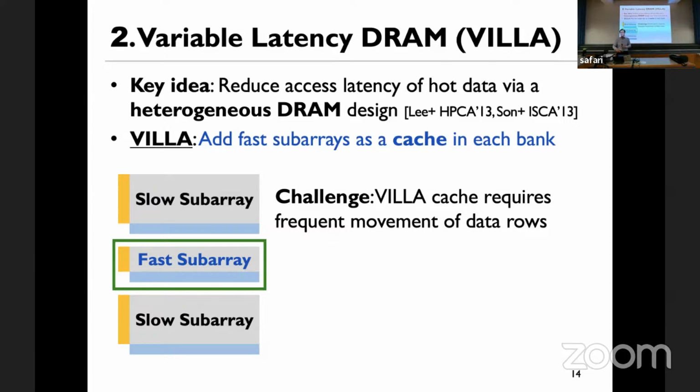Yes, please. Well, with this configuration with the fast subarray, could we maybe then only integrate Mbit in the fast subarray? It is because this will be equivalent to when we have a processor, we basically have caches. So in this case, the cache is a fast subarray, and so the computation would be done in the fast subarray. Potentially, yes. Yeah, sure, potentially. That could be a design decision. If you're cost sensitive, for example, you may just decide to put Mbit only in the fast subarrays, right? But if you're not that cost sensitive, it doesn't hurt probably to do it everywhere. But yeah, it gives you some more options in terms of where you can potentially integrate. Good question.